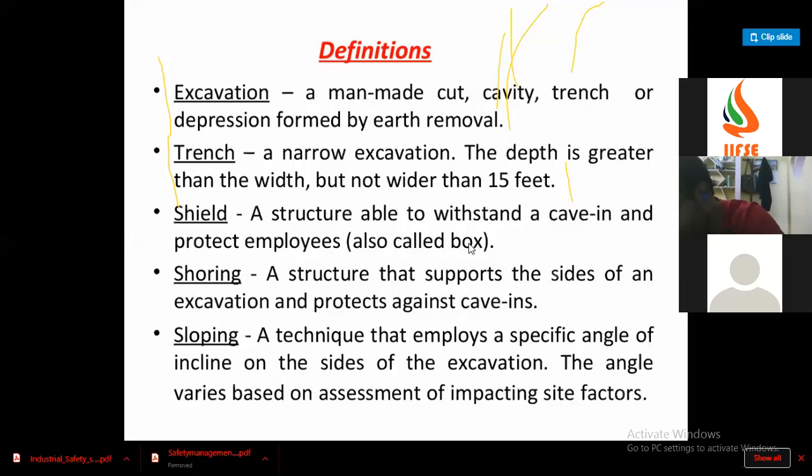Sir, if you're working in a brownfield or somewhere similar, even for half a meter or 2 meters, it's not a matter. Before starting the activity, we need to go for a gas test based on the permit and the requirements. We can judge based on the situation, the environment, and the permit requirements. If they are working near a gas plant, it is a hazardous area, brownfield, so it is mandatory.